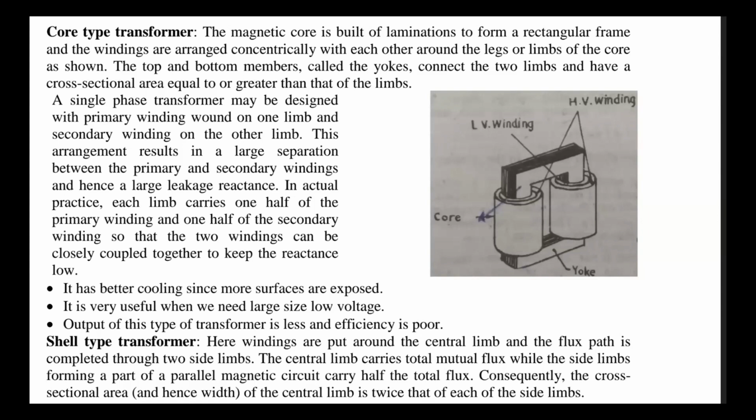But in both cases, as the area is increasing, the cooling will increase. So this is the advantage of core type transformer over shell type transformer.